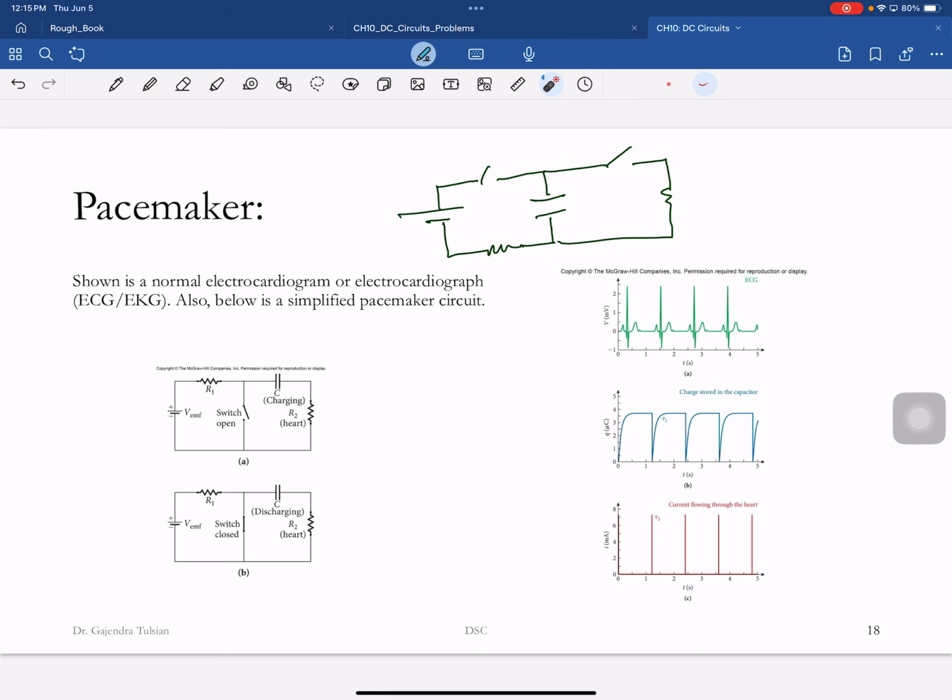What if you want to go for a run? You lower the resistor even more. Yeah, so you want to charge this faster. Let's say now you want 120 beats per minute, so you want the capacitor to charge in half a second. Okay, so you need to come up with a way of making this resistance adjustable.